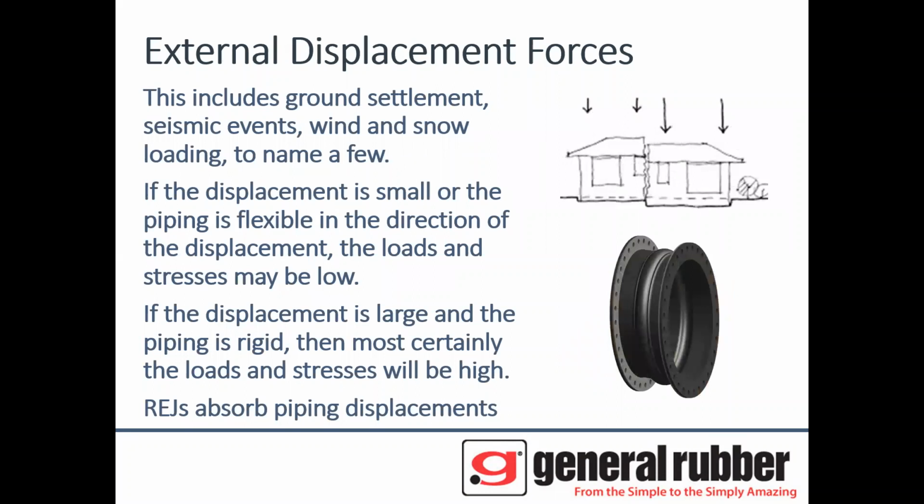External displacement forces. This includes ground settlement, seismic events, wind and snow loads, to name a few. If the displacement is small, or the piping is flexible in the direction of displacement, the loads and stresses are low. But if the displacement is large and the piping is rigid in that direction, then the stresses will be high. So rubber expansion joints absorb pipe displacements, and yes, a performance EJ will do this that much better.